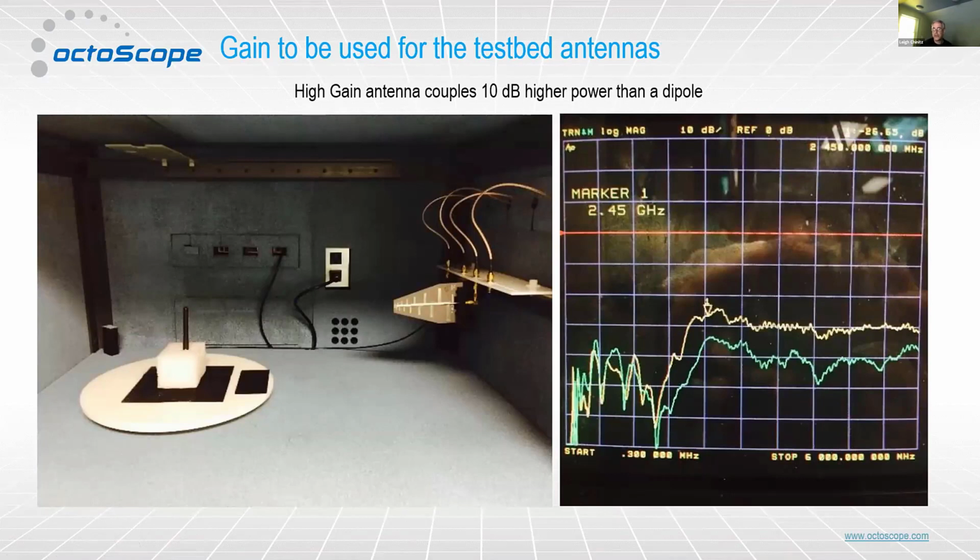So we've done the over-the-air part now. We know that free space is an extremely good model for that. What about these antennas? Anyone who's used our test bed knows we have these high gain antennas that are very commonly used. So we know that as part of the link budget, they're going to contribute to those gain terms. So how much gain should we assign for these? Well, we have those measurements as well.